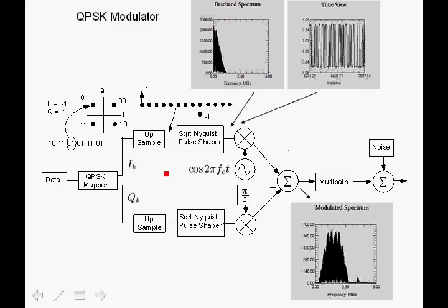At the receiver, every symbol would be mapped back to 2 bits, but in the case of BPSK, every symbol will be mapped to a single bit. So the more points in the constellation, the higher our throughput. For example, if we had a 16 QAM system, then every point in the constellation is represented by 4 bits, and the symbol rate would be the bit rate divided by 4, and our throughput would be 4 times the throughput of BPSK, or binary phase shift keying.